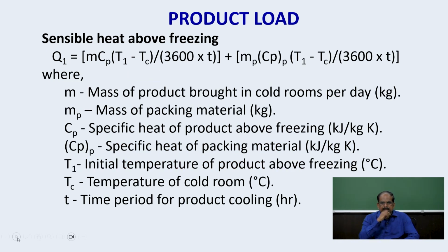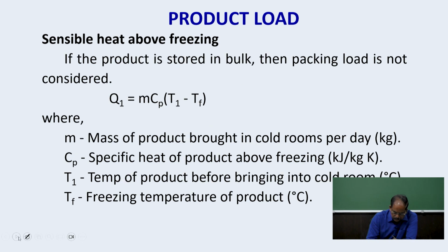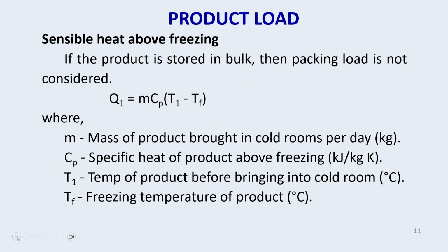Sensible heat above freezing. So, let us see the formulas which are used for the product load. Sensible heat above freezing, here I am taking as Q1. There are 3 components.